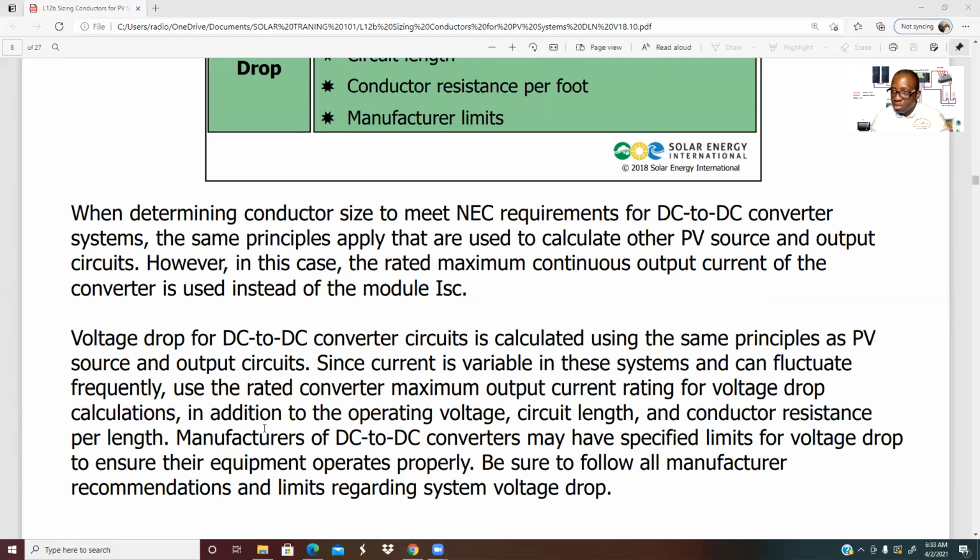Be sure every wiring, every conductor, every socket has manufacturer requirements. They tell you how long a run, what distance, what temperature. Read about whatever wiring or sockets you are purchasing so you can know what the manufacturer recommendations are. Very important.